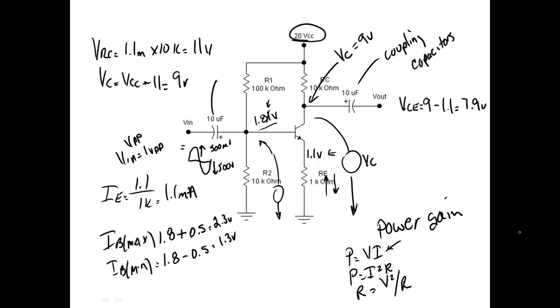Y'all understand? Okay. So what we're trying to do is, if the input resistance to the amplifier and the output resistance was the same, then if we got a voltage gain, we would get a power gain. But what we'll do in a minute is we'll try to figure out what the signal sees as far as the opposition it sees, and then we'll see what's going on. Everybody okay?